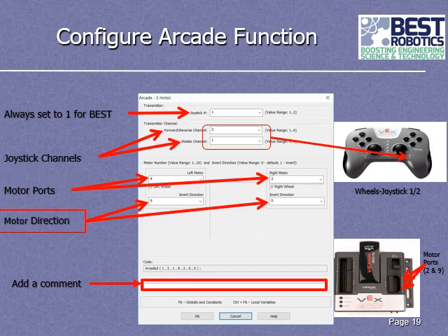The motor direction, typically you won't have to do anything here. If for some reason one of the motors was wired improperly or something and it was running opposite from what it should, you can actually fix that problem by coming in here and switching the 0 to a 1, which will then invert the direction that it moves. I don't really foresee you having to do it, but this is one place where you could go in and fix that spin direction so that it's the correct direction.